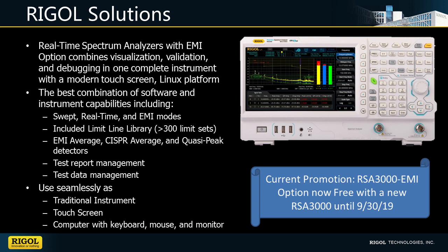So now we've looked at all of our visualization, validation, and debug tests across radiated, conducted, and immunity compliance measurements. So that really shows you that we can debug everything from simple radiated emissions using a power supply and looking at the cause and effect of a switching power supply's conducted noise, to our radiated emissions, and finally to using the full capabilities of real-time mode to look at time-correlated debugging that we can do with both a scope and a spectrum analyzer together.